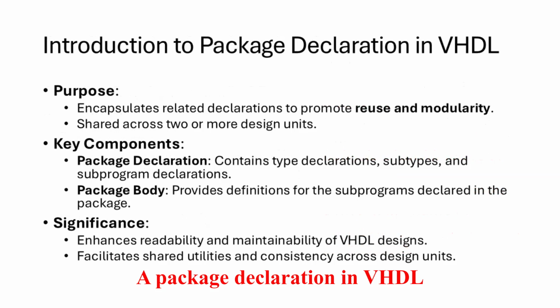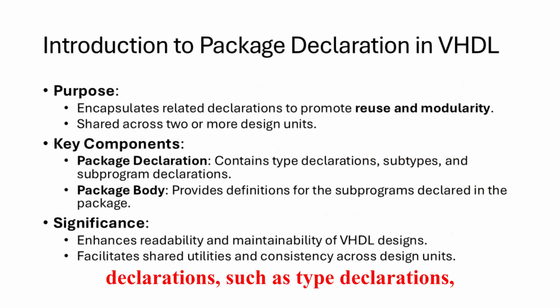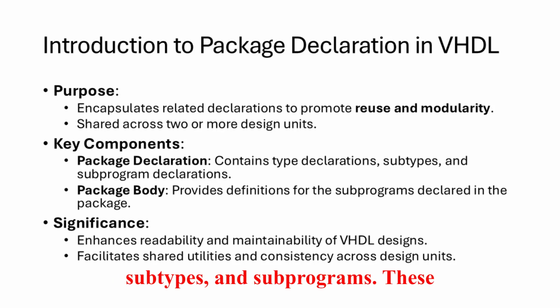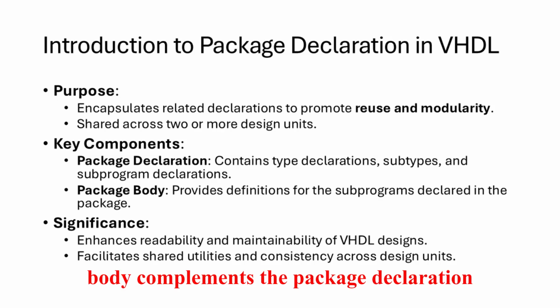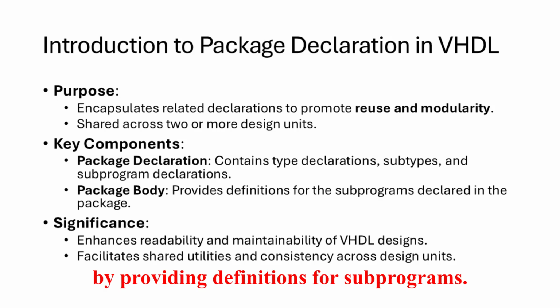A package declaration in VHDL encapsulates a set of related declarations, such as type declarations, subtypes, and subprograms. These declarations can be shared across multiple design units, enabling modularity and code reuse. A package body complements the package declaration by providing definitions for subprograms.